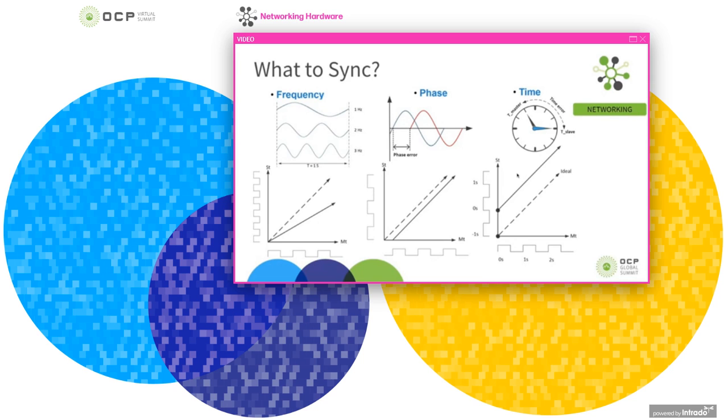And for the time, you can see the minimum unit here is seconds, because it is a relatively long range in timing. So it is much easier to deal with, maybe through an I2C system or SMBus. So I don't think time synchronization will be a problem in our topic. The major targets are frequency sync and phase sync. Here, we aim to deal with frequency sync through SyncE and phase through 1588. We will introduce it on the next page.